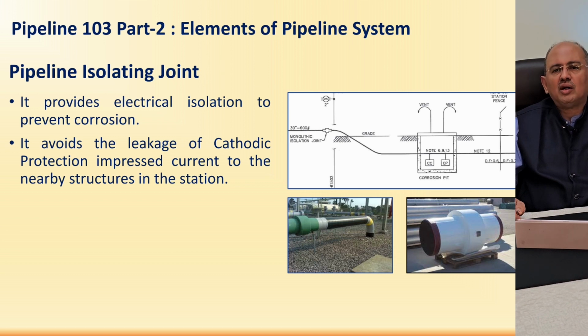Wet soil and dry soil can create some kind of a medium across which a galvanic cell can form, and on the same pipe, an anode and cathode pair can form, and it can exchange the ions, and then one point will lose the metal, the other point will get the metal.